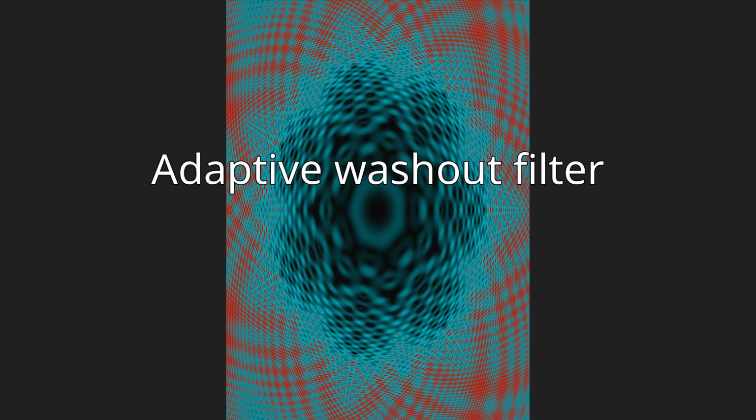Adaptive washout filter. This adaptive approach was developed at NASA Langley. It is made up of a combination of empirically determined filters in which several of the coefficients are varied in a prescribed manner in order to minimize a set objective cost function. In a study conducted at the University of Toronto, the coordinated adaptive filter provided the most favorable pilot ratings as compared with the other two types of washout filters.